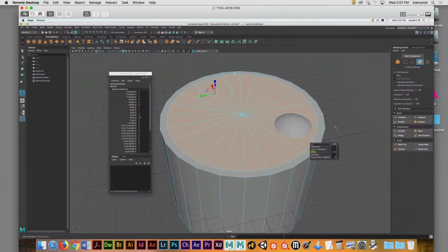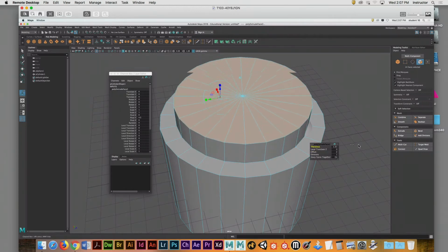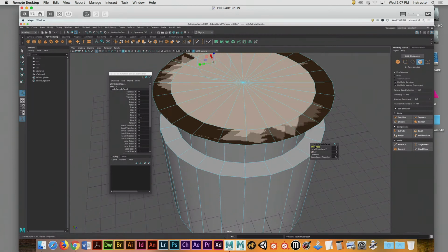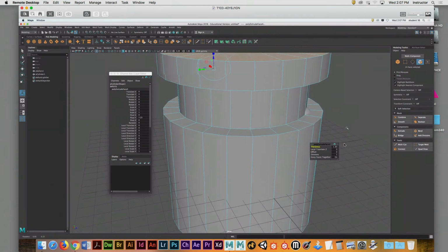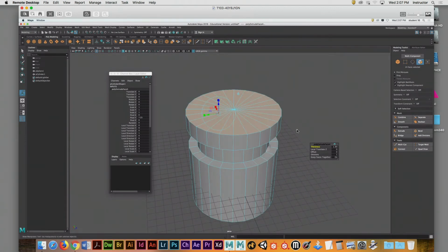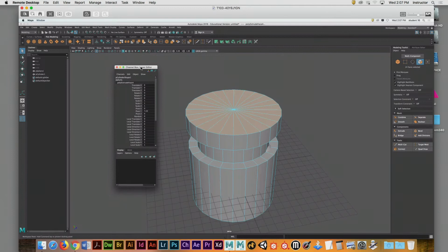What I'm going to do real fast is some very simple modeling on this, just to give us a whole series of inputs. Does anyone remember how to repeat a tool, to reapply the tool over and over again? The G key. So I'm going to do another extrude, and this time I'll just do an up, and then I'll hit the G key again, and I'll do an offset going the other direction, G key, and yeah, let's just call that a day. Q key to go back to my selection tool, and life is good.